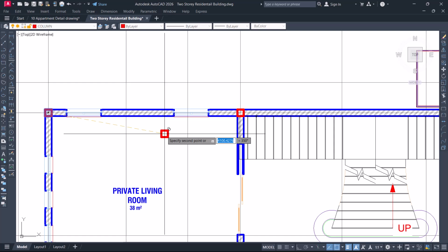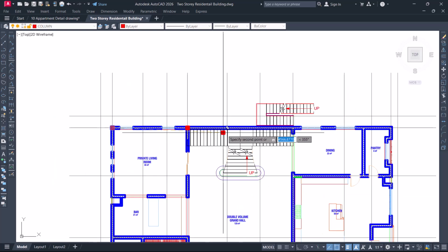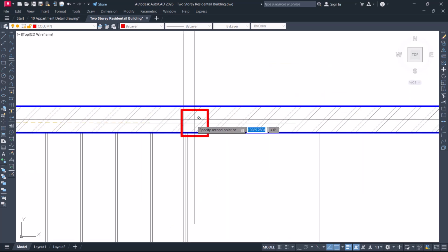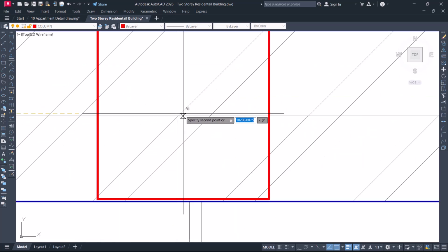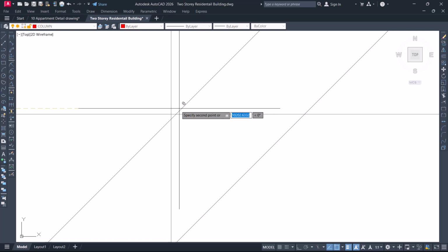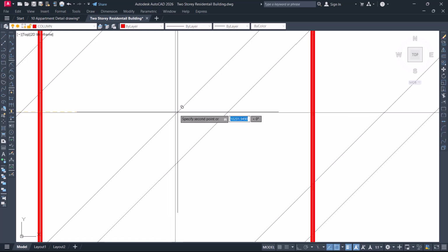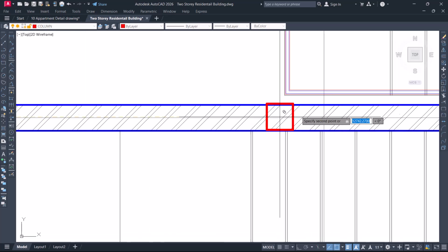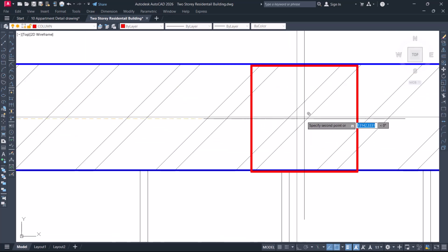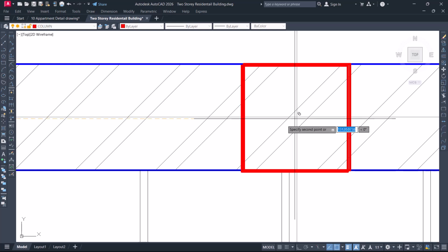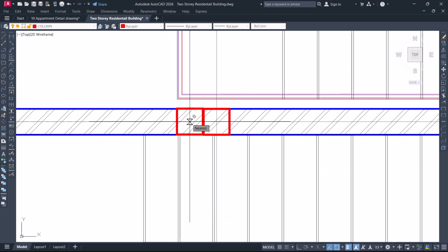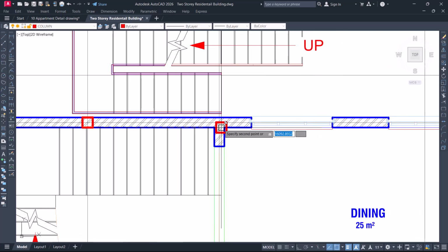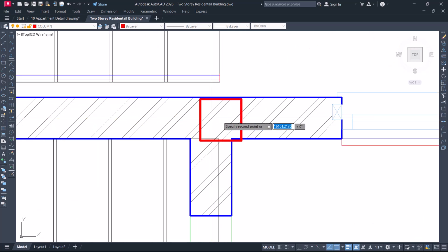Okay, that's fine. So with that now, I'll be placing my column points first. Then later, I'll begin to look out for areas where I feel I want to add or remove columns. So I'll come now and place them. Make sure your columns are placed at the middle of the grid line, except you want the column to be flush, maybe on the left or on the right. But apart from that, make sure they are placed at the middle.